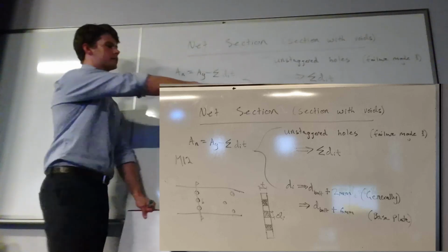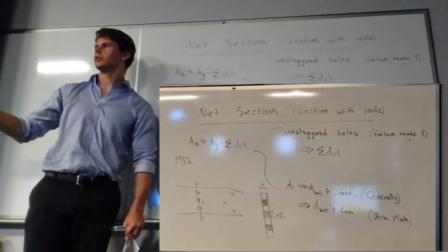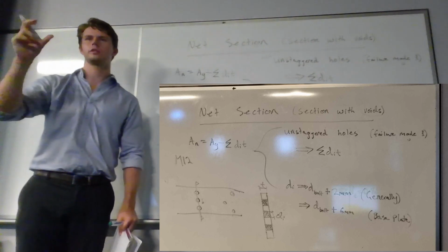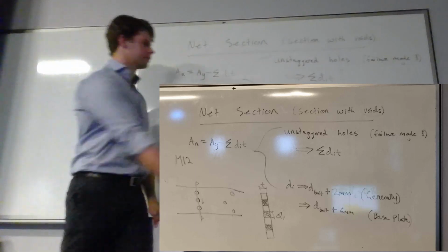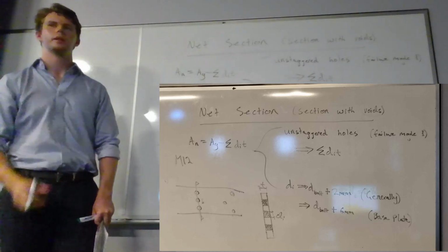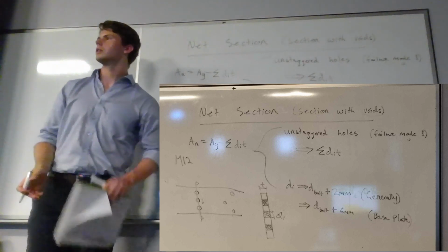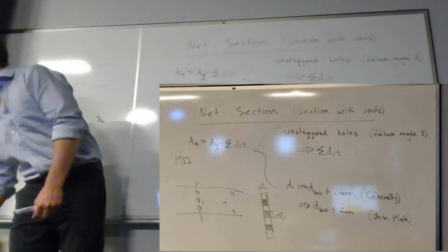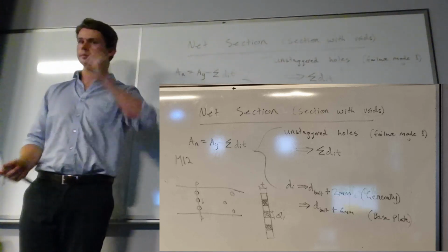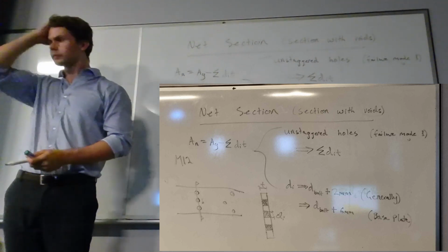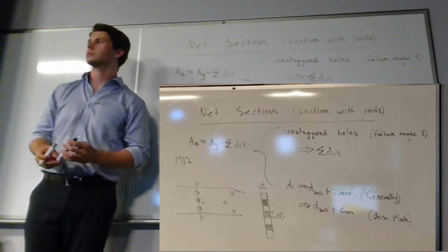Now, we also add 2 mm for bolt holes. I think that's just because of the threads of the bolts, so it's a bit of extra tolerance when you're calculating that area. Then there's a special case for base plates, where you add 6 mm, because bigger bolts generally have to do with the installation method. With a general purpose bolt, you drill a hole in the plate, but the hole won't be the same diameter as the bolt, because then it may not fit.